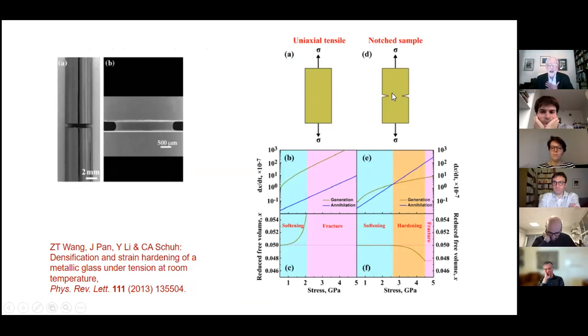In this case, you build up lateral tension as well around the notch, so you get a triaxial stress state with the shear components being rather low relative to the hydrostatic. So you get less plastic flow, but a much higher hydrostatic tension than you get here. So in terms of generating damage, that's rather slow here.